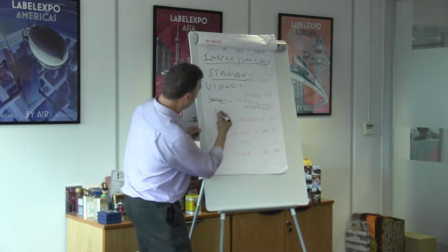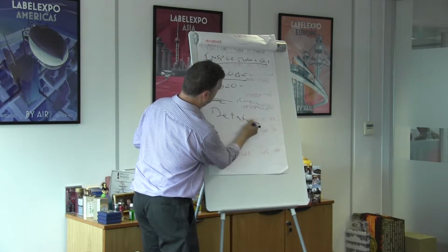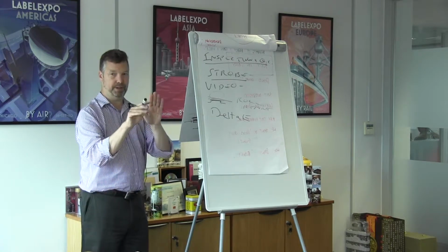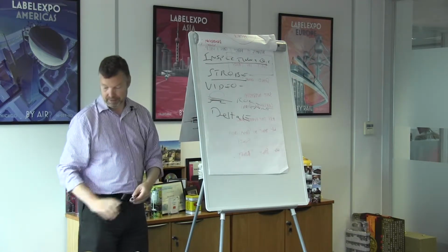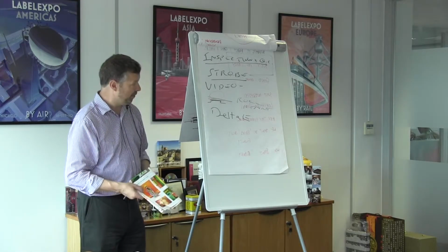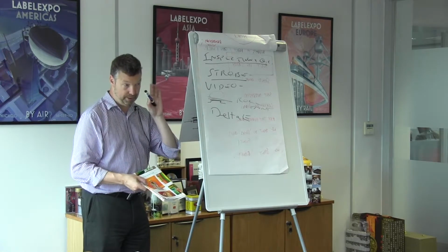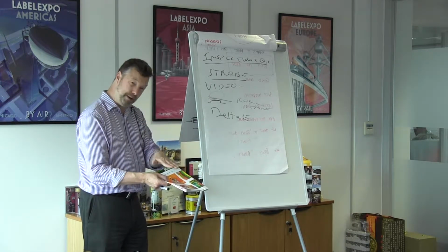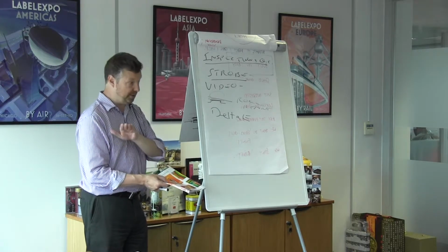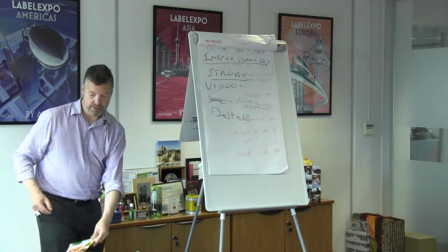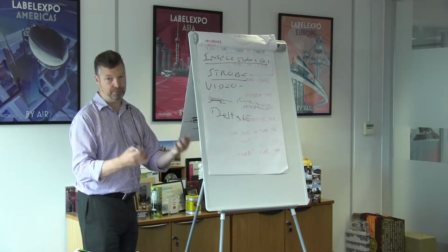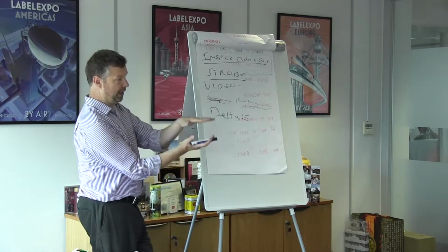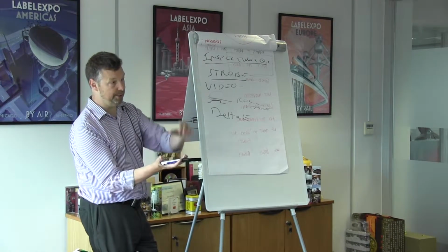And if you may remember, cast your mind back to a thing called delta E. Delta E is a measurement of color for when we humans start to see a variation in color. So if two of us are looking at that orange, around delta 3 is where the human eye starts to perceive a color difference. So you can have slight variations of color up to delta 1, delta 2. Get to about 3, you start to notice it. By the time it gets to 5, you can definitely notice that there are two different shades of orange. So what the AVT camera is doing, and now Bobst and now Ultramat and all the other guys, they've all got the same systems now, it's measuring that color and saying, if two humans were looking at that color, would they be able to see a difference? And as soon as that delta gets beyond 3, the red light goes on.